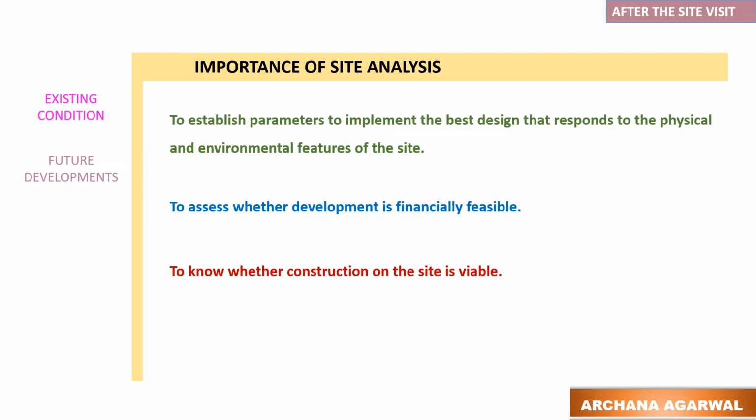An architectural site analysis looks at issues such as site location, size, topography, zoning, traffic conditions, and climate. The analysis also needs to consider any future developments or changes to the site surroundings, such as a change of road designations, changing cultural patterns, or other significant building developments within the area. Understanding the site context is very important for an architect to make informed decisions about the design development.